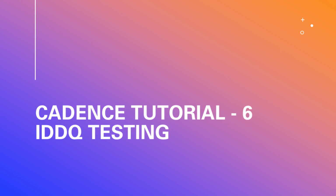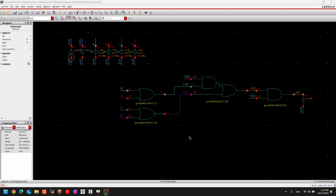Hello everyone, this is Abdullah, and in this video, I will present what IDDQ testing is. IDDQ testing is based on testing the stuck-at faults of an arbitrary circuit. You have a combinational circuit or a sequential one, it doesn't matter. But in this case, you want to test the IDDQ because if there are any stuck-at faults at any nodes available in the circuit, and you want to know if there is a stuck-at fault or not, use IDDQ testing.